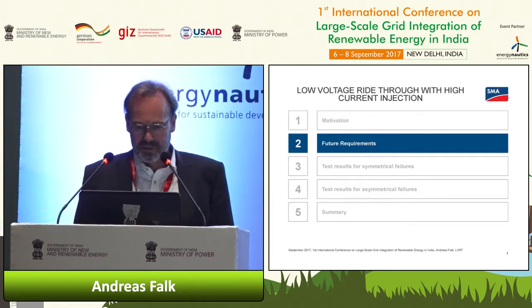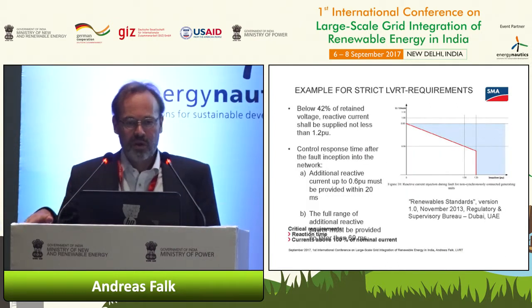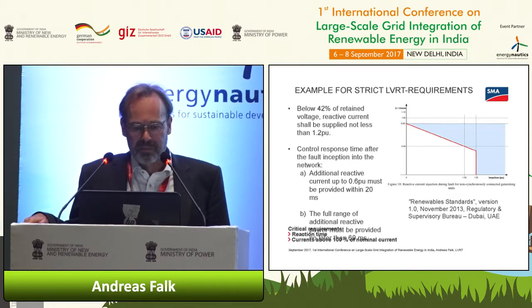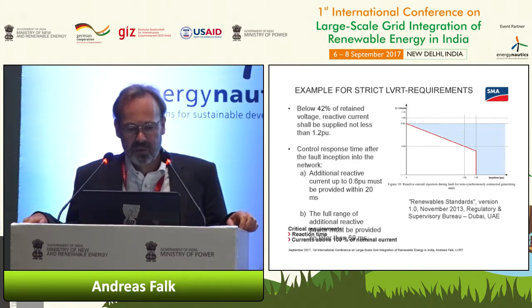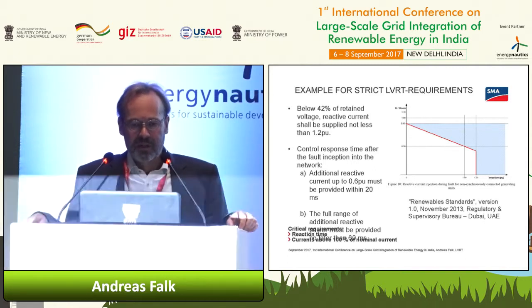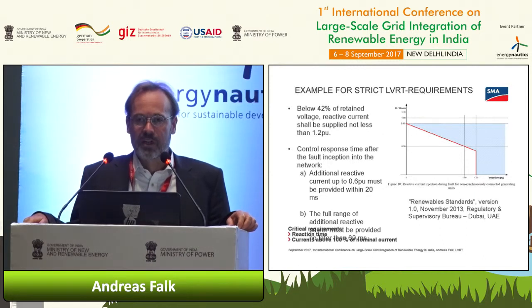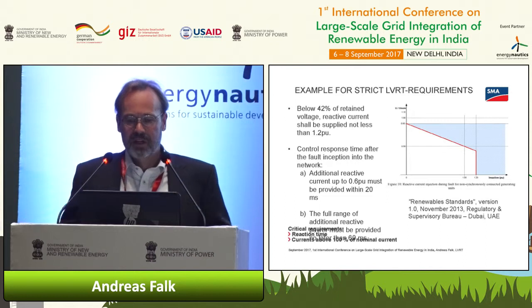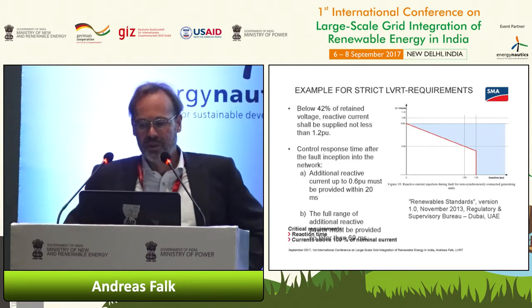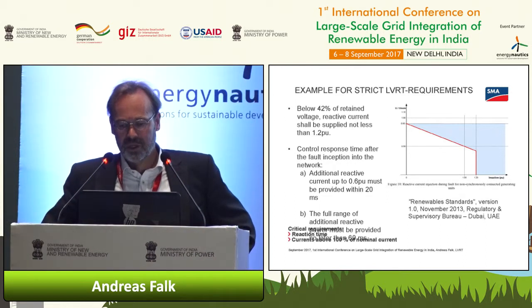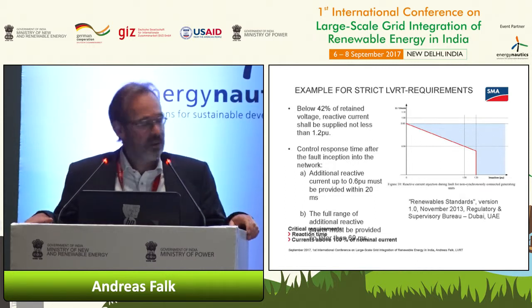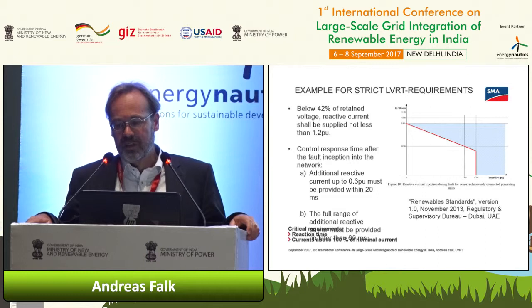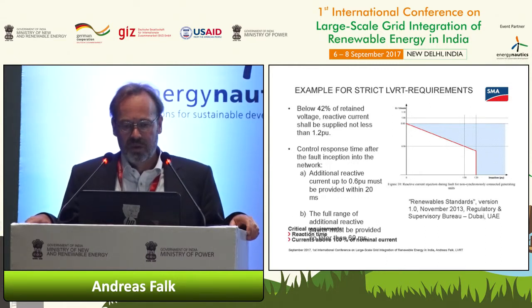Future requirements. Up to now, mainly the requirements require 100% of the nominal current during voltage dip. But there are coming up new requirements, for example, in Dubai, which require 120% of nominal current during a voltage dip.